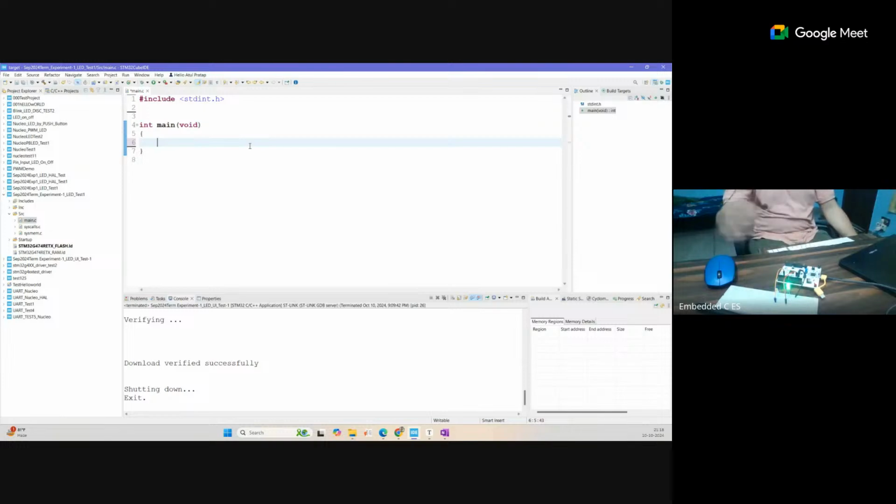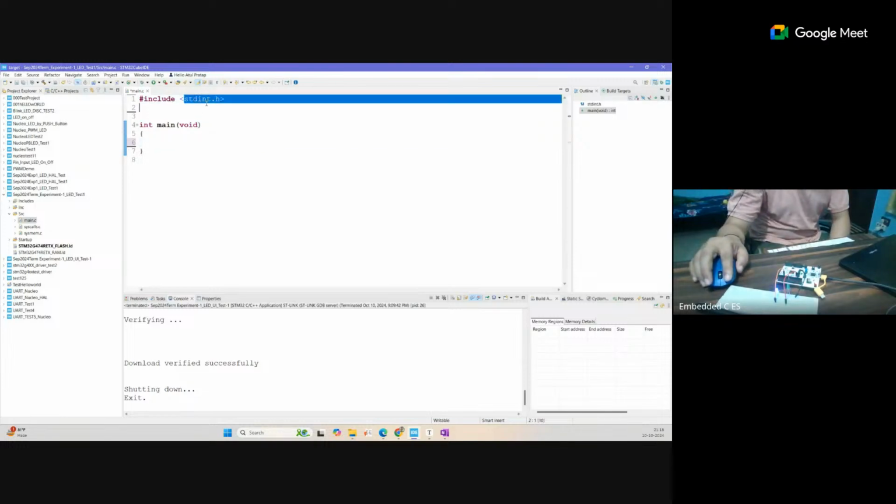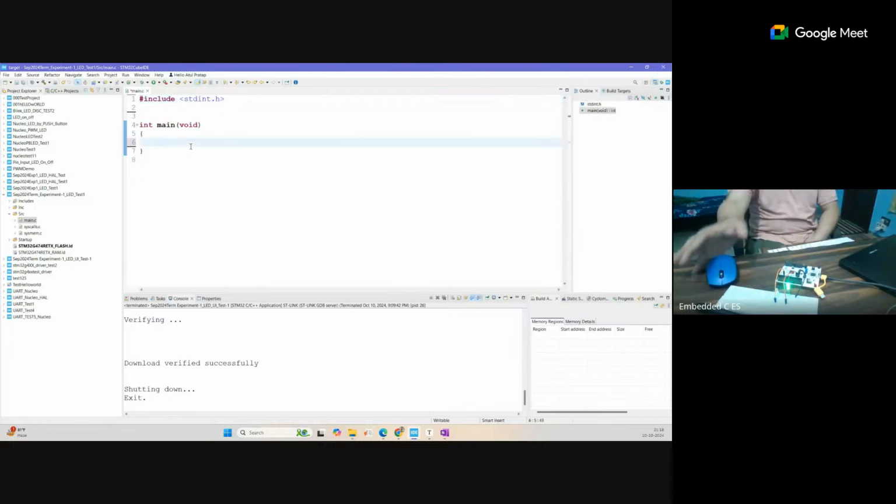So what we will do is use some standard types. That is one library. Here we will use the type where it is 32 bits, if we are using 32 bits. That will remain the same on each type of machine. That will not change, because on the microcontroller, if a type takes 32 bits on one machine and we are working according to that, but we use the same code on another machine where the same data type takes fewer bits, that may create a problem. So we will use some standard, so our bits will remain the same for our data type.